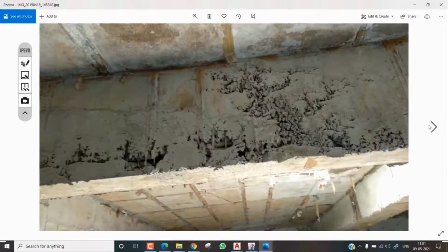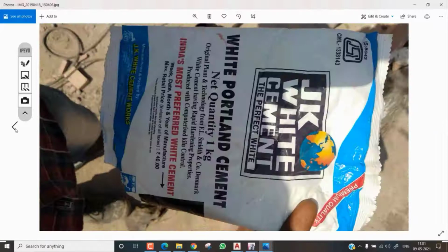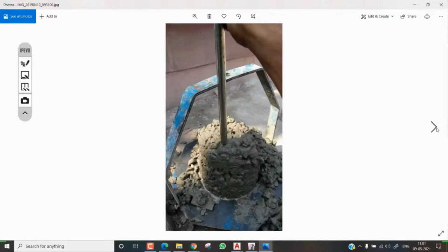So after that, this is a type of thing that happens on a site actually. Whenever there is improper vibrating, we will get some type of issues here. At that time, what we need to do is go for micro concreting. If you go for micro concreting, we need to touch up. Okay, we call it a touch up on site. So we need to use the micro concrete and fill all the gaps. Okay, so micro concrete gives you the strength, that is some JK you have seen, right? So this is micro concreting. Okay, so based upon that mix, we will do this slump test.